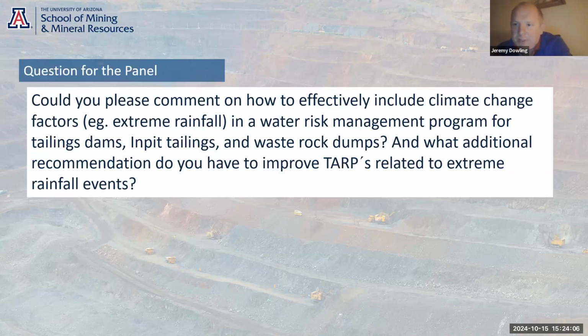And even if the 1 in 100-year storm is still the same amount of rain over a 24-hour period, the concentration of the intense period of rainfall is becoming much more intense, and so the same statistically generated storms are creating much more severe storm events and aggressive erosion and problems with really the peak flow and the destructiveness of the peak flow related to erosion and sediment control.